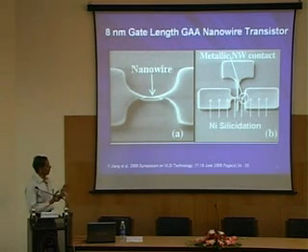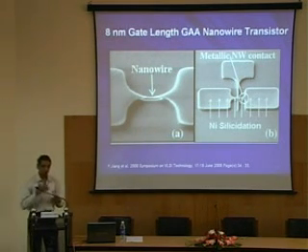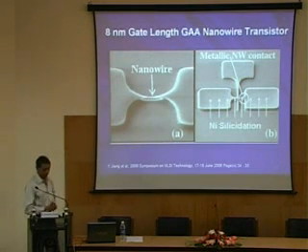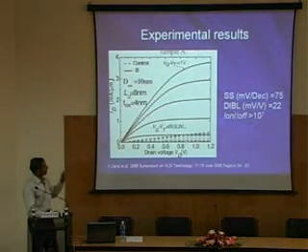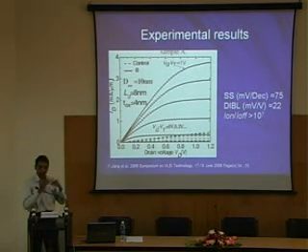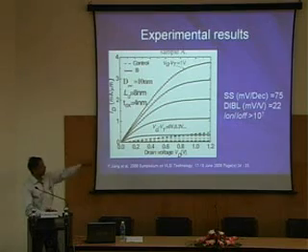So there are all kinds of efforts. Use the existing CMOS technology or use alternate methods in order to grow these nanowires and then make the logic circuits. These are the typical characteristics of a MOSFET made on silicon nanowires. They have realized a very large on-off ratio for these silicon nanowire based transistors, which is very, very good. We wanted to have a good difference between on and off state, and that is defined by this on-off ratio.